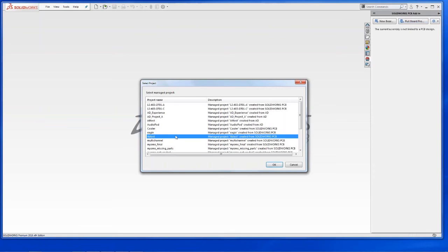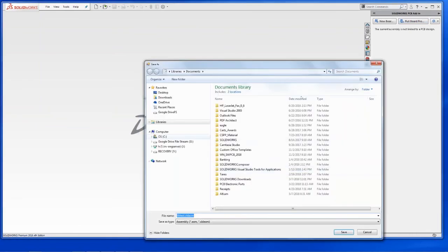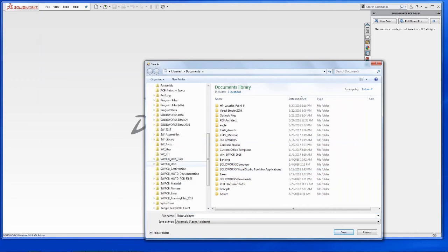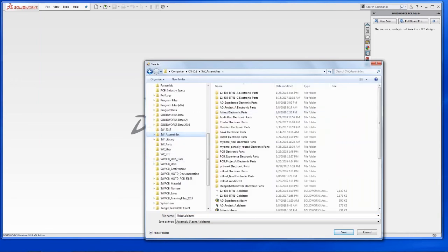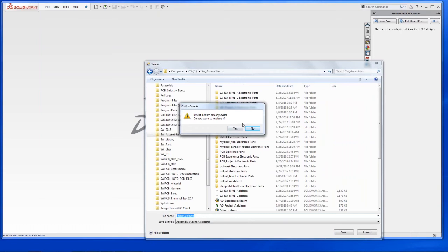The project we're working on now is a library test project, and we're going to put that into our SolidWorks assembly folder. SolidWorks will always ask you, hey, where do you want to save this assembly that I'm about to create? And you can choose. You can save that assembly directly in PDM. The beauty of that is it also puts the models in there for you.